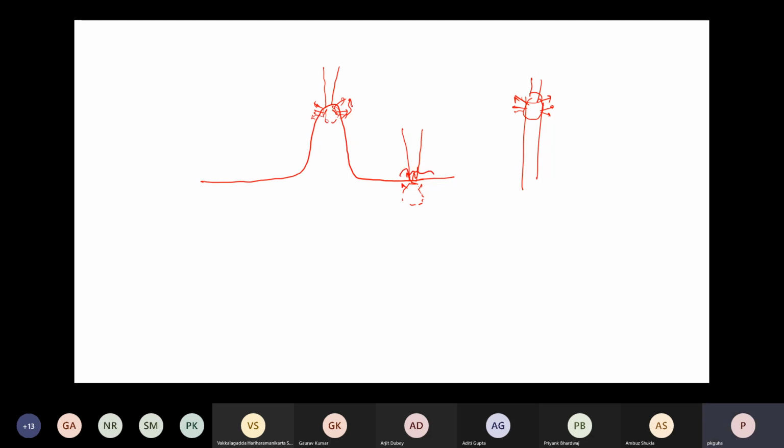So the flat portion will give you a darker impression, whereas these kinds of nano protrusions, nano wire, nano rod structures will give you a brighter impression. So that is how, from capturing the secondary electrons, you get bright and dark portions, or in effect you generate the image, right?